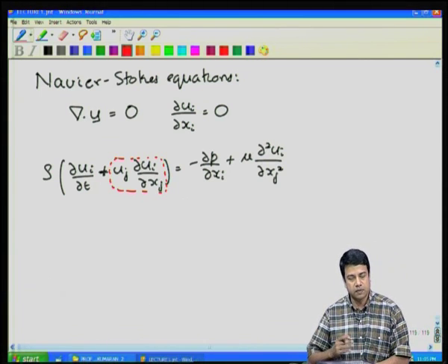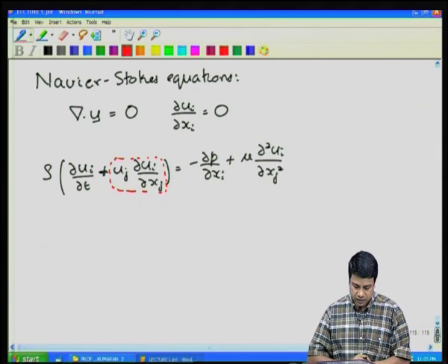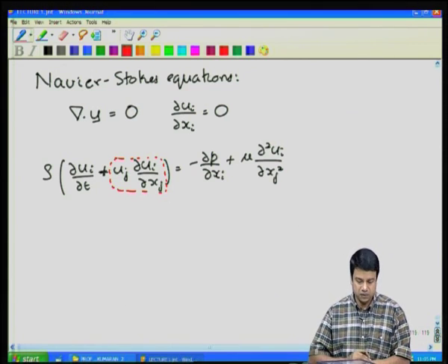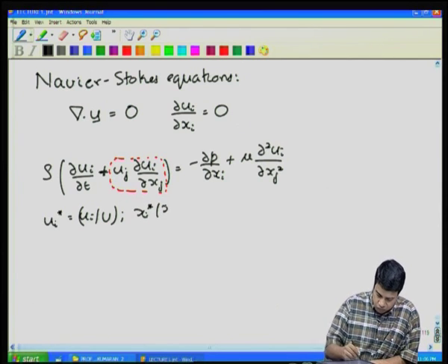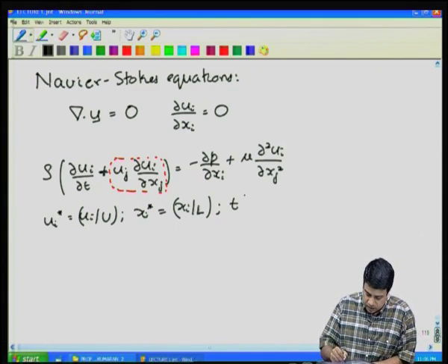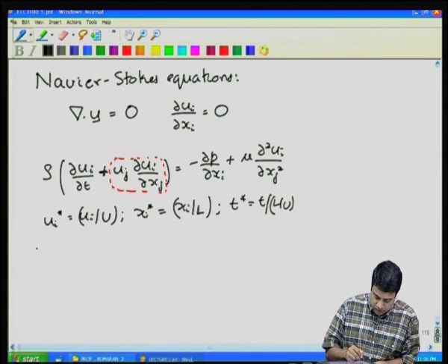So, when you multiply the velocity by a factor of 2, not all terms multiply by that same factor, and therefore, they are nonlinear. Okay. We can consider this in different limits. As I showed you in the last lecture, if we scale this equation, we scale the velocity by a characteristic scale, the distance by a characteristic scale, and due to this the time gets defined as L by u. If we scale it in this fashion, then we get the scaled equations as Re partial ui by partial t